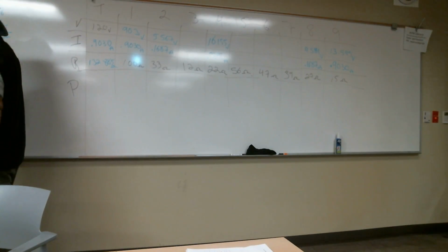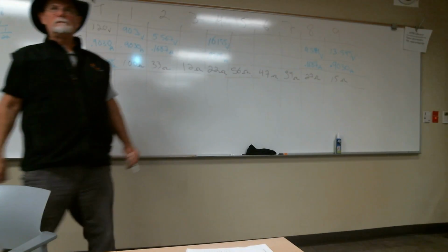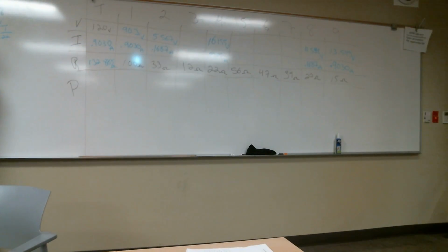We're going to take 29.7 and subtract 5.567. So that's going to give us 24.7 minus 0.556, which is going to be 24.14 something. 24.133. Okay, 24.133 volts. That's the node voltage here and here.